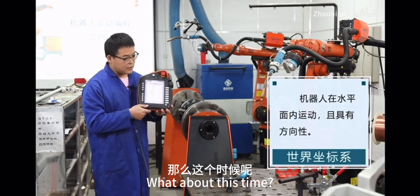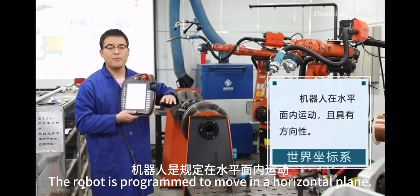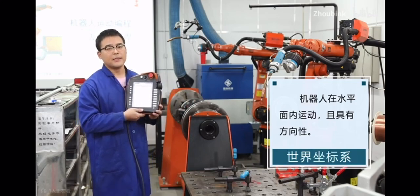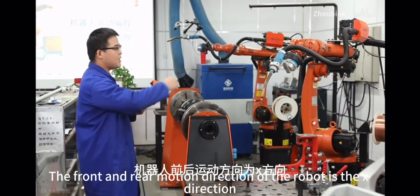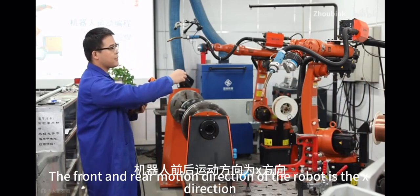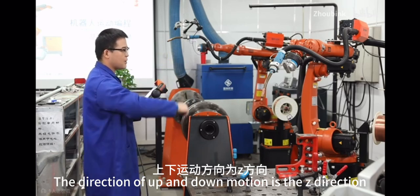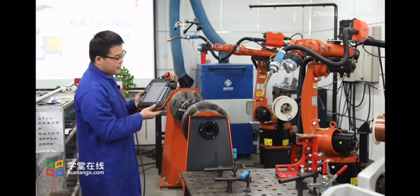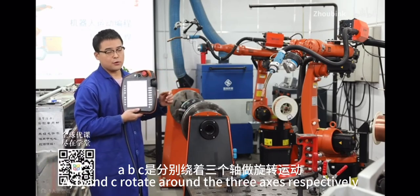At this time, the robot is programmed to move in a horizontal plane, and it is directional. So how is it stipulated? When I stand facing the robot, the front and rear motion direction is the X direction. The left and right motion direction is the Y direction. The up and down motion is the Z direction. A, B and C rotate around the three axes respectively.